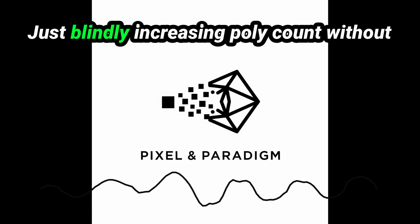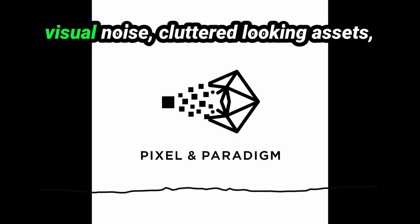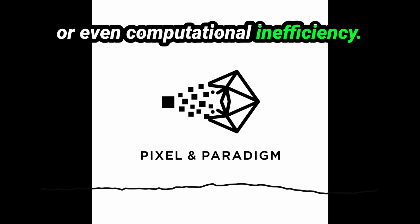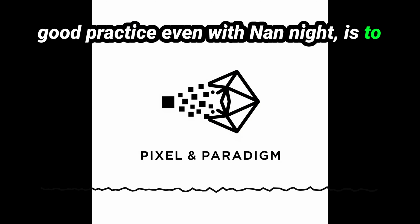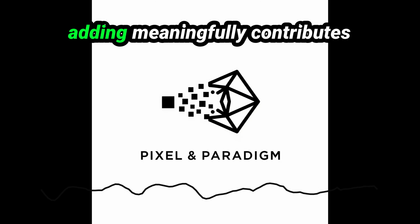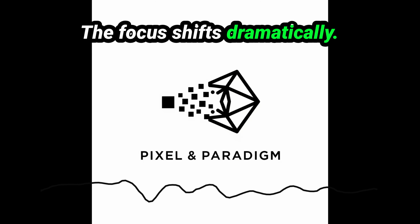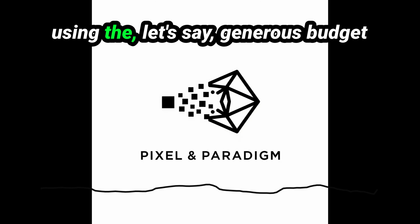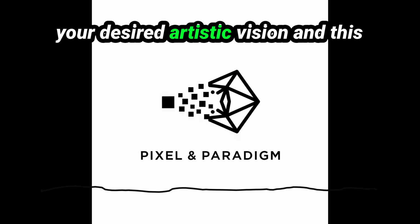Exactly. Just blindly increasing poly count without clear artistic direction can easily lead to visual noise, cluttered-looking assets, or even computational inefficiency, believe it or not, even for Nanite. Good practice, even with Nanite, is to maintain a degree of artistic optimization. Make sure the geometry you're adding meaningfully contributes to the final visual experience. The focus shifts dramatically. It's no longer about minimizing polygons at all costs, but about using the, let's say, generous budget intelligently and purposefully to achieve your desired artistic vision.